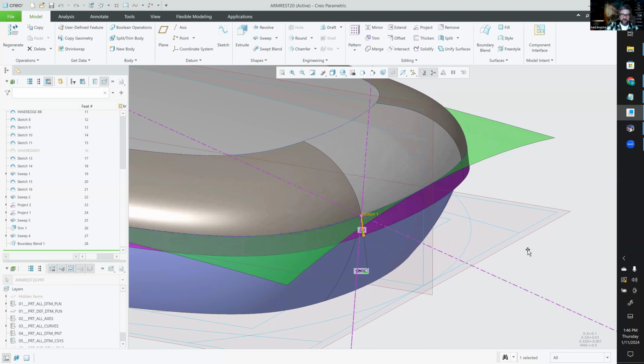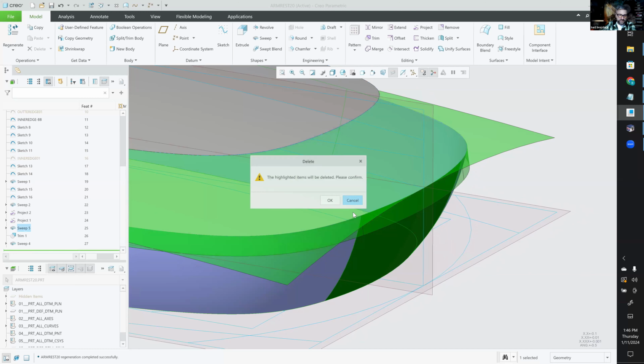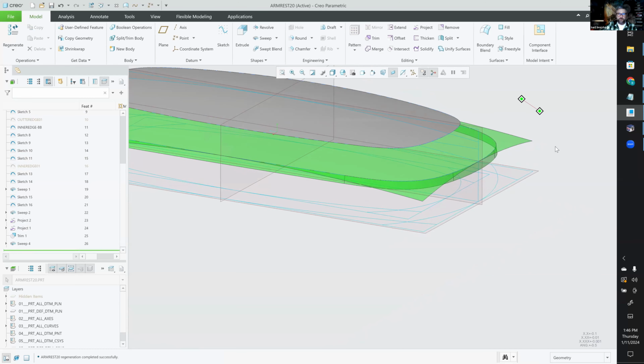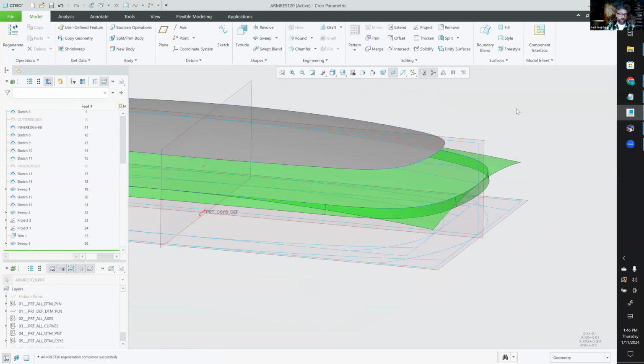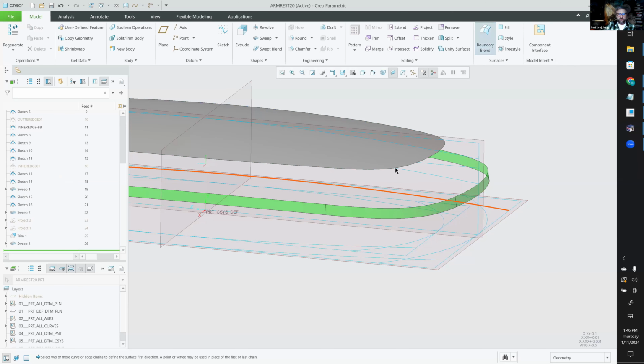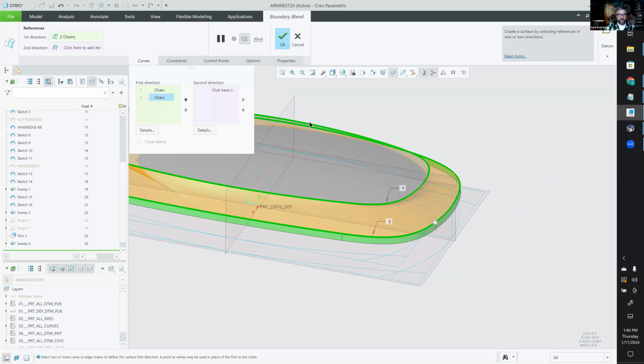So that's a crowbar. Now I'm going to delete this surface here, and I'll delete the bottom one too, just to get my example more simplistic. This is what we call a parting surface. It's the parting surface that generates the parting line. I'm going to color it green like I do, and hide it. If you've got any experience in surfacing, what I try to get young people to do is hide the projected curves first, and then generate these geometries. Here, I'm going to hit the shift key to get up there, control, and then shift to get all the way around.